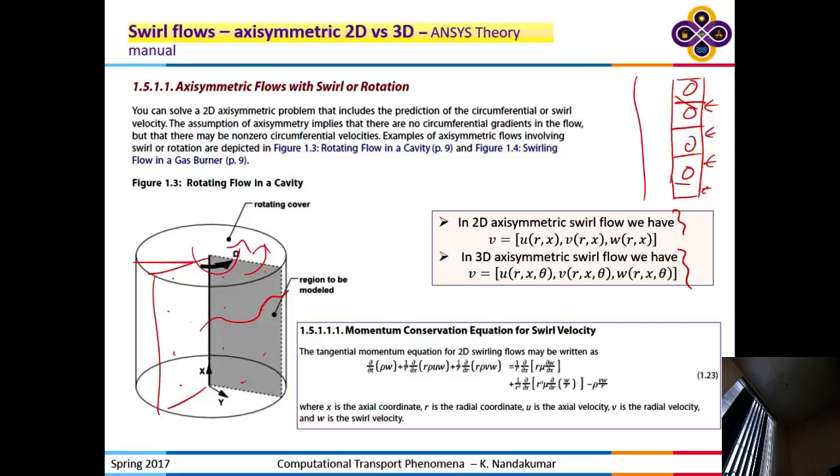That symmetry is also broken once you exceed a certain rotational speed, and then you get these waves. And these waves will have a finite number of modes as you go around, and they will close on themselves in 2π. Okay? And these can be moving in time, then you get a traveling wave solution. And that's what makes this Taylor-Couette problem very, very rich in dynamics in terms of possible solution patterns.